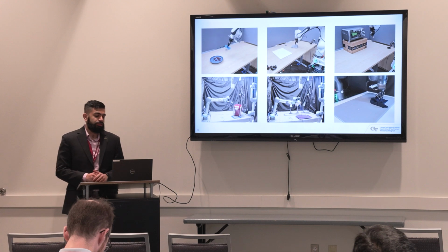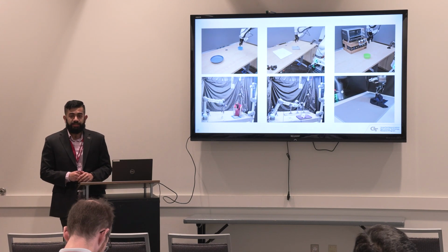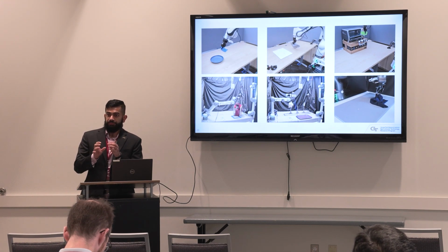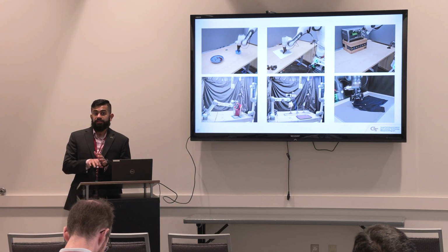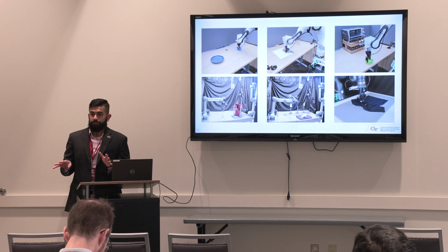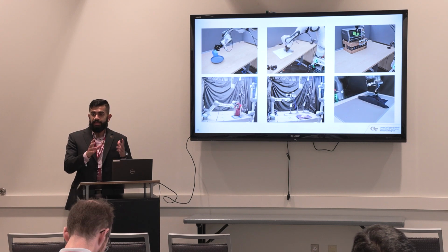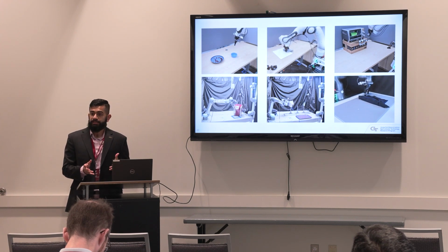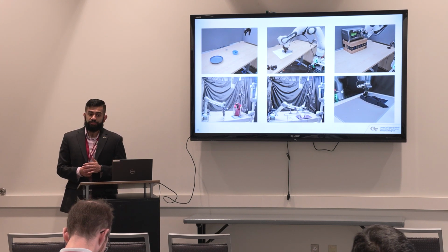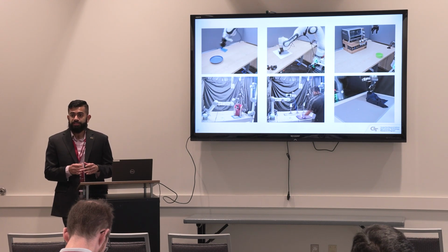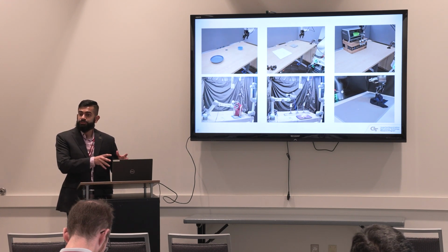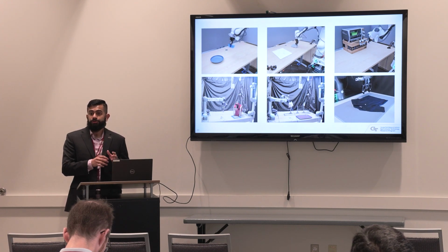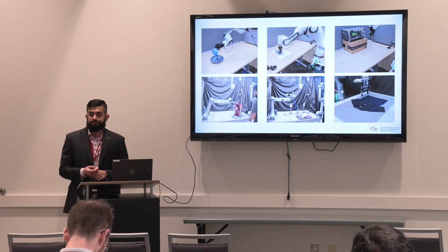Different lighting, that's a great question. With the end-to-end models, it can be a little brittle to different lighting conditions or distractors. So the way we get over that is we collect data in all different conditions, right? Or we try to find a way to maintain a consistent lighting or consistent environment. Some of our newer models are a little more robust, especially if we pre-train our vision encoders on a ton of data. We find that they're more robust to different lighting conditions.